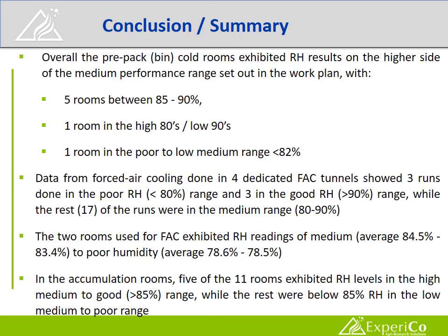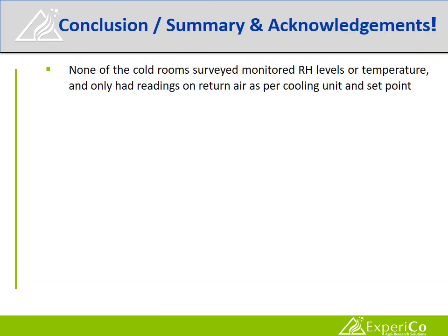In the accumulation rooms, 5 of the 11 rooms exhibited RH levels in the high medium to good range, that was above 85%, while the rest were below 85% in the low medium to poor range. None of the cold rooms surveyed monitored RH levels or temperature, and only had readings on return air as per cooling unit and set point.